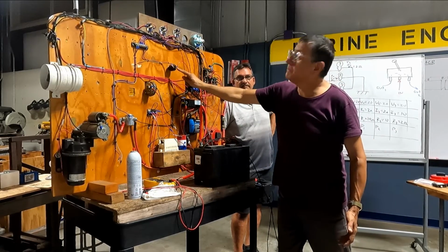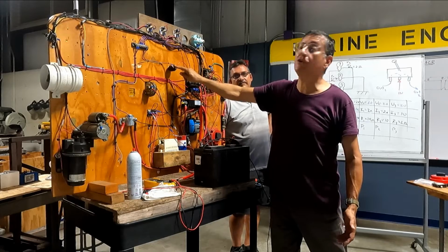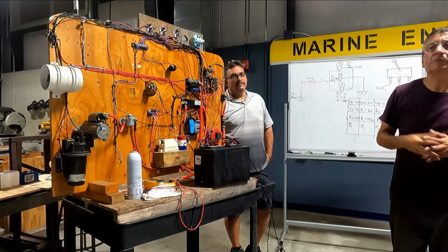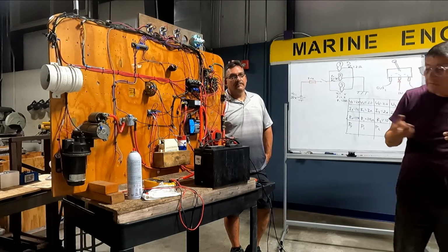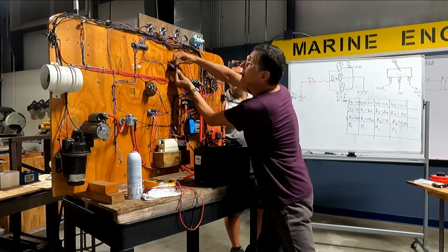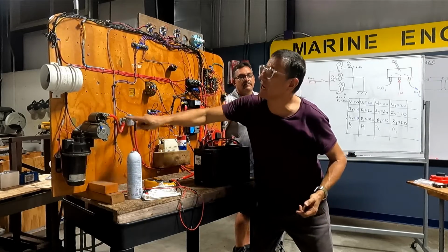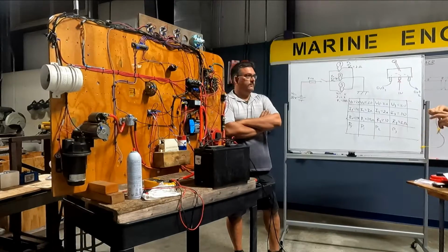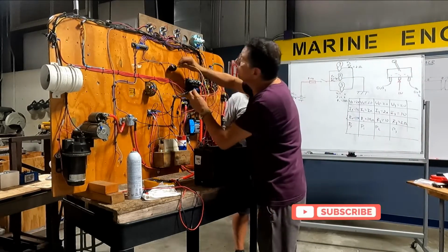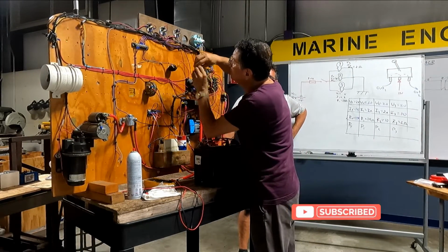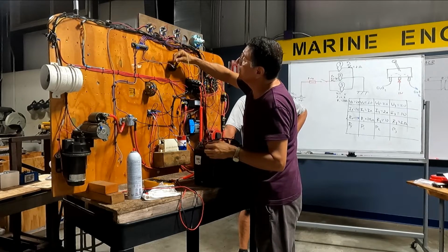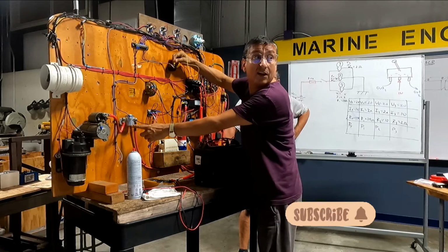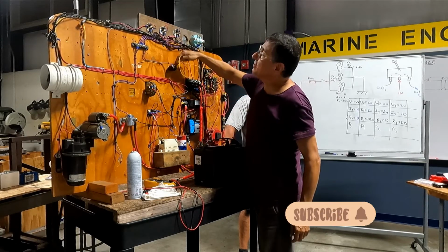When you turn it on, you have power here, but when you select the first position, you don't have power here in ignition. What is the problem? The ignition switch. Let me jump it with a wire, this with this. Immediately I have power here and I hear the click. My ignition switch is damaged. With my jumper cable, right now I hear the click, no? It's damaged, my ignition switch.